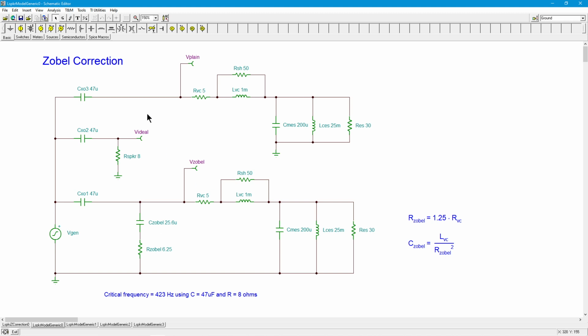Now, we're going to look at 3 things here. We're going to look at the ideal response curve, a Bode plot for that. And this is first order, so this should be rolling off at 6 dB per octave, 20 dB per decade. Now you're saying, hey, I'm not going to use a first order. I'm going to use a second or a third order, or maybe something more complex than that. The reason I'm using a first order is because this spreads out the transition region and it's easy to see. I'm not suggesting that you should use a first order crossover. It's just that for our purposes, this is a really good illustrative tool. You'll be able to see exactly what's going on here very easily.